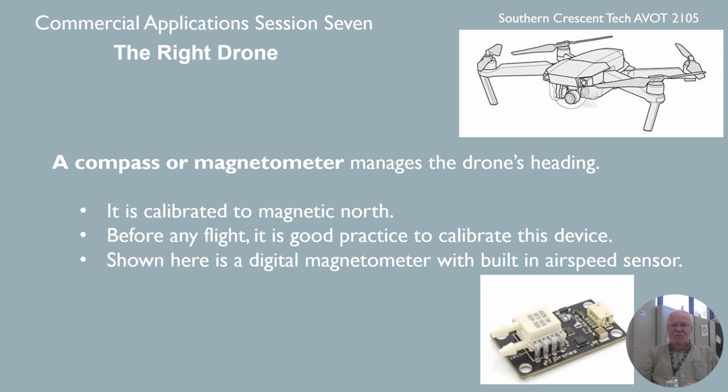The magnetometer manages the drone's heading. Okay, it's calibrated to true north. Before a flight, especially if we're going to be professional pilots, we need to be actually doing this every time before a flight.